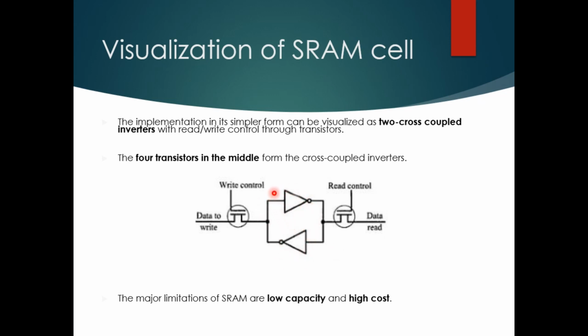So I have here 1 as my information, I will get 0 here. If I have 0 as information, I can get 1 here. So I can retrieve 1 from here if this was 0, and I can retrieve 0 from here if this was 1. Obviously, if this end is 1, this end will be 0, because this is an inverter. The 0 is fed to the inverter, and I have this 1. So you can see that it is bistable, that is 2 stable states, 1 and 0 are stable here. Getting?